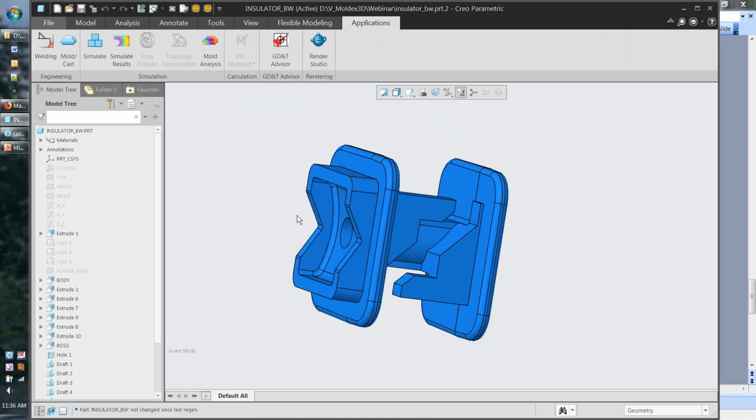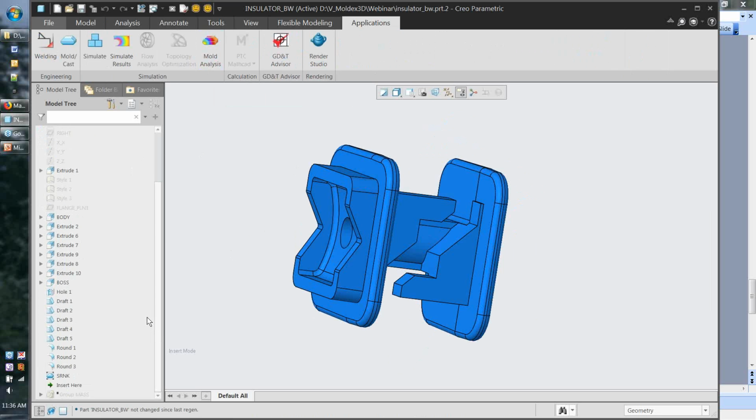If you have previously designed work and would start using Creo Mold Analysis on those previously designed parts, that would work just fine. There isn't any preparation or any special sauce, if you will, that goes into the part in and of itself. The parts are just simply Creo parts. You can see the feature tree that exists here for this part that I created for the purpose of this demonstration. It's just a simple feature tree. There is nothing here, or nothing needs to be here, for the purpose of mold analysis itself. We simply